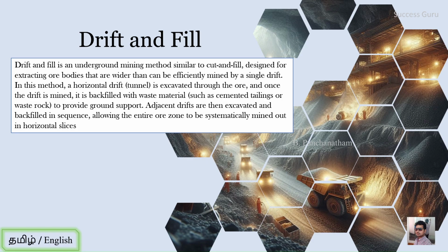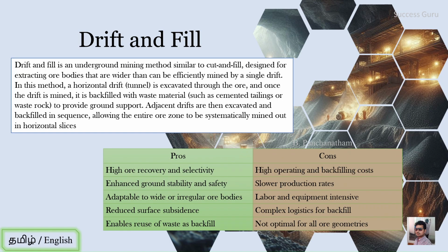Let us see the pros and cons of this method. The very first advantage is that as we are fixing the length, breadth and height of the tunnel or drift, we have a very good range of selectivity, and the recovery is also very high. The second advantage is that it enhances ground stability and safety. We are refilling it once again, so this ensures the safety and stability of the ground.